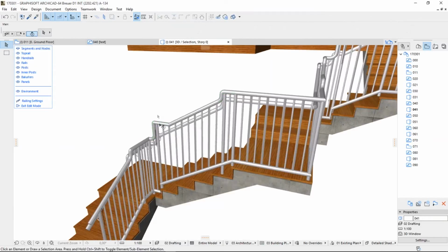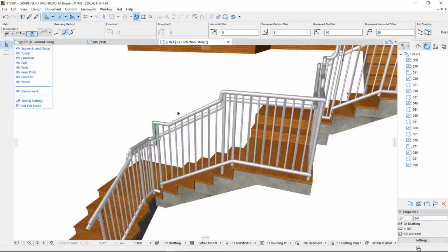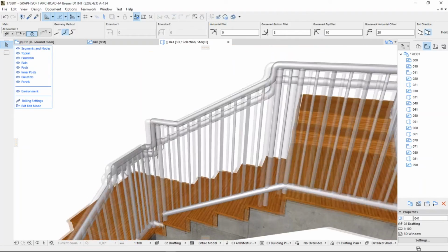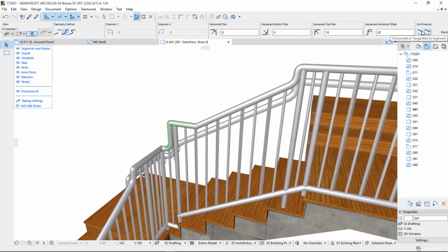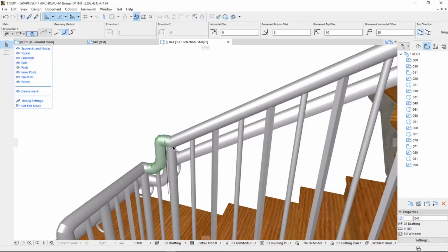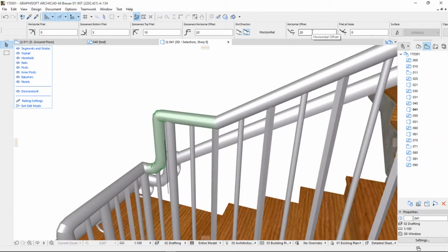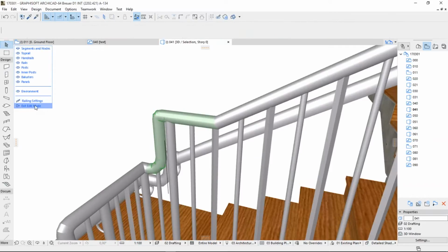It's really changed a bit. And now if I click on this one, only this one is highlighted. So let me go back and for example, if I change this direction type, you see that it goes actually down here. So it goes up until the node itself. But if I add a little extension to it, so if you slide your hand down, it may stop before the node or the post, and there will be a small horizontal part that you can add to it. So these are just a few set of parameters, and feel free to try them out if you have the chance.